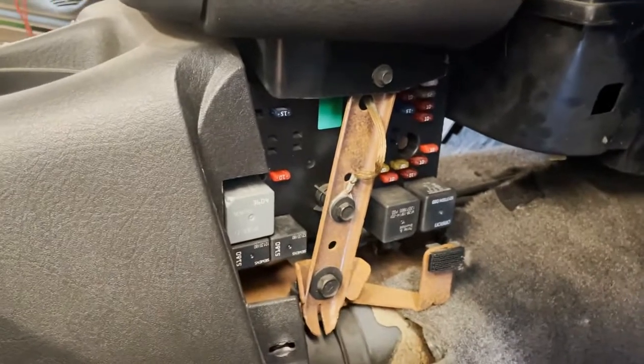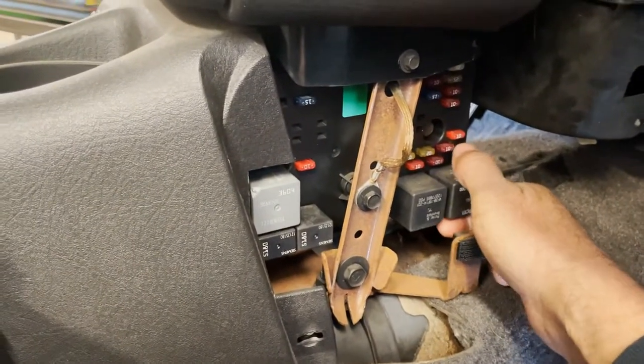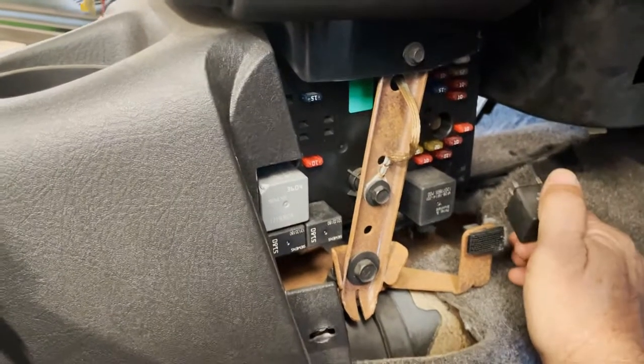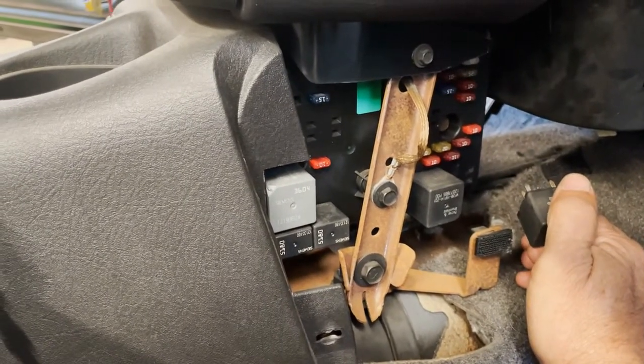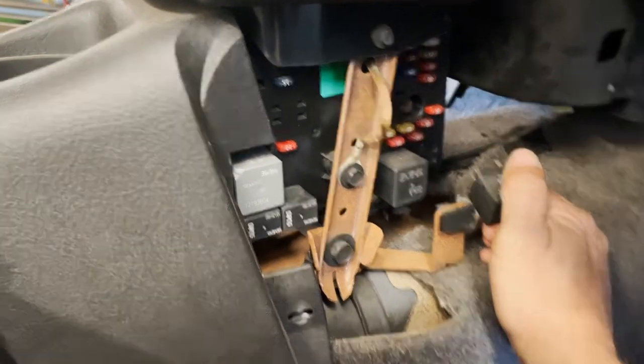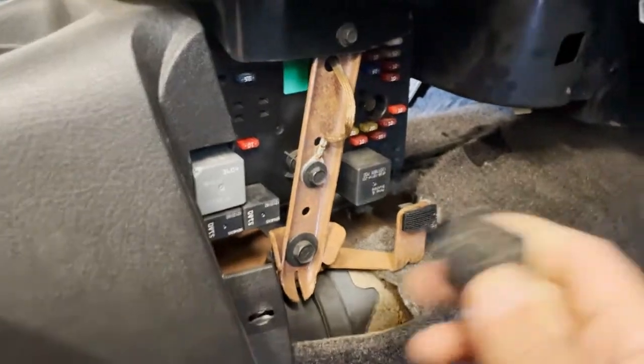So Mike, can you go ahead and give me some power on that window? Turn the key up. Okay, I'm rolling it. I pulled one of them out. Is it still stopped? No, okay, wait, no. It's not working. Stopped, so I pulled the correct one, and that's how I find out what relay it is.